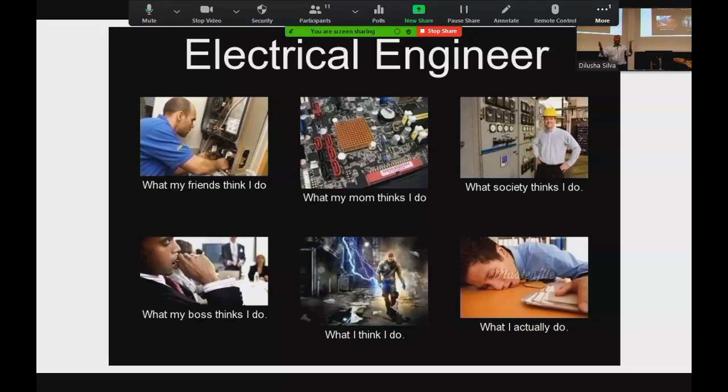Yeah. So to sort of circumvent some of the problems nowadays, we have a thing called an RCD. Every house has them, residual current device. To be honest, it was a bit of a cop-out for the industry. It's not good engineering. It was brought in and fixes the problem where a fuse works quickly. You can have an MCB, or miniature circuit breaker, that will sit on a fault for quite some time, seconds, when a fuse is gone, and allow enough voltage to get through to actually do harm. So you invented something called a residual current device. Right? And that sort of circumvented most of those problems, but didn't overcome the overload protection problem. Right? So unfortunately the industry's moved on from fuses, more commercially than anything.